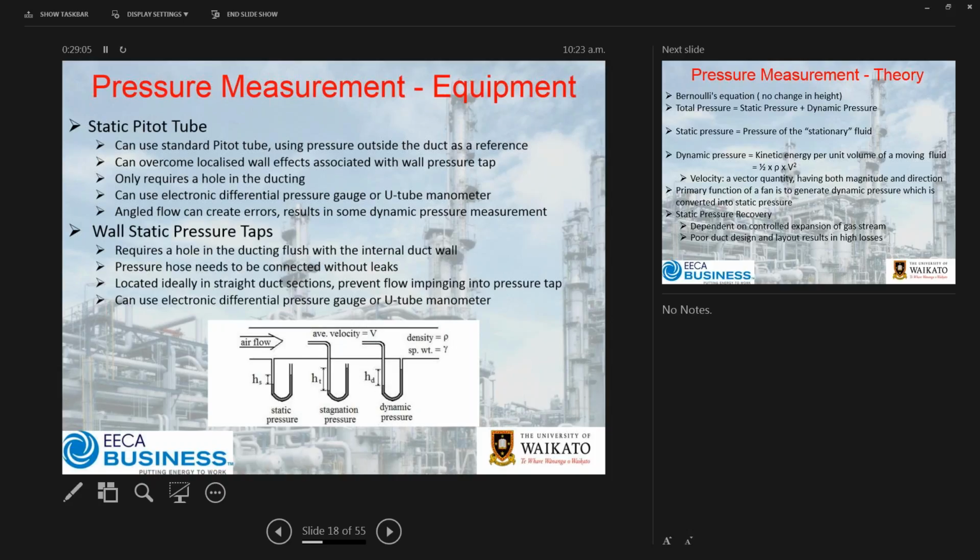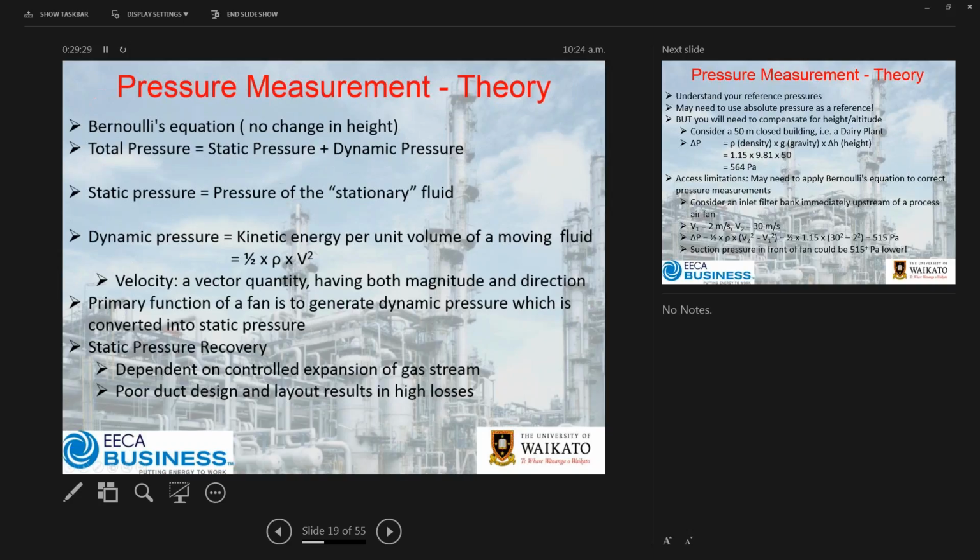It means you don't have to worry about losing fluid out of your U-tube, whether your U-tube is big enough, and lining up millimeter scales to get your heights and all the rest of it. You don't need to worry about changing fluids for different pressure ranges. And if you've got limitations in your pressure ranges, you can get multiple DP cells with a range of pressure bands to meet what you need.